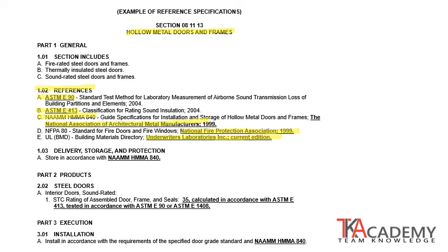And then for each system or for each part, for example here, delivery, storage, and protection, store in accordance to NAAMM HMMA 840. So we don't tell the contractor what to do in this case. We say to do it according to this standard. And so the contractor has to go back and look to see what this standard is up here to know what the appropriate action is here with storing these products on site.